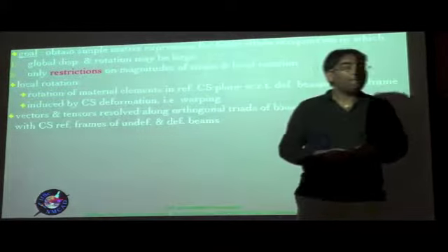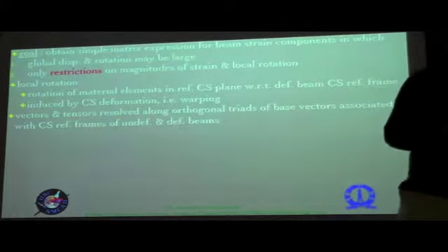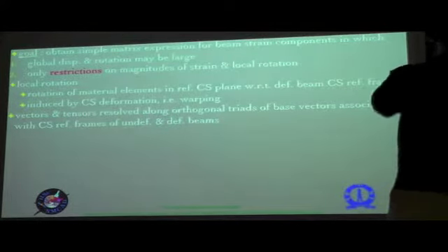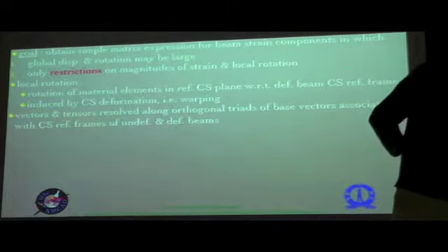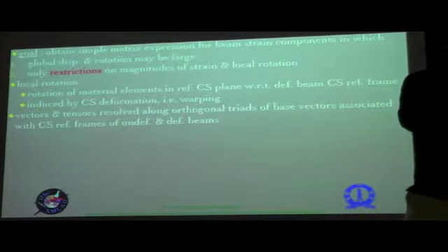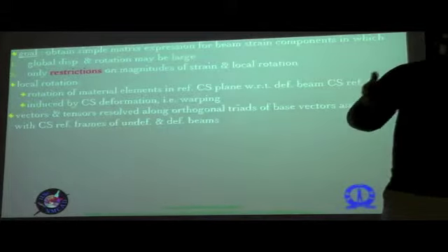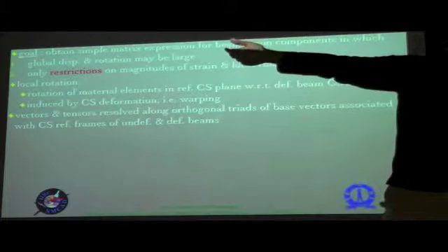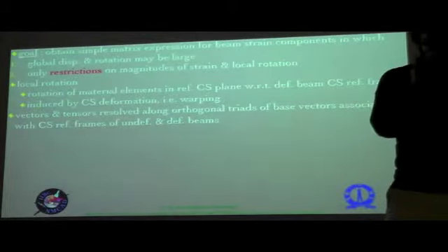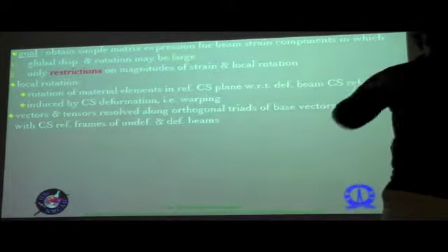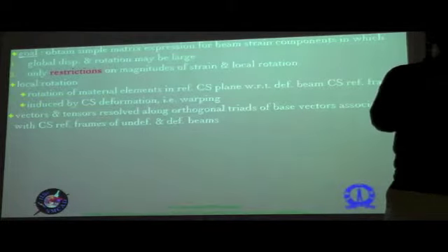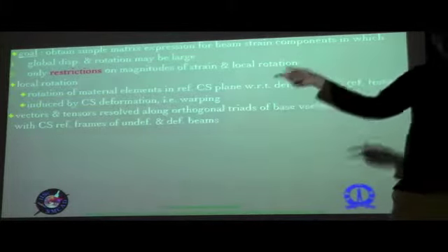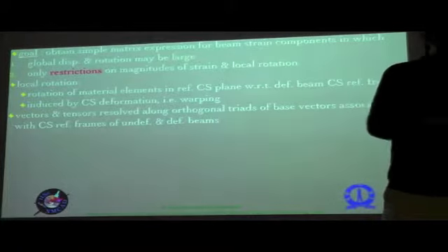So is this restriction also applicable in the case of hyperelastic material? For hyperelastic materials, the strain that you have to talk about has its own limits. The restriction on strain is basically for elastic materials. For hyperelastic materials, there are some materials which can go all the way up to 400% strain, etc. In that case, the maximum strain epsilon is not a small quantity compared to unity. So you have to completely drop that out and deal only with the geometric small parameters that you have in the variational asymptotic method. So many of these conclusions that we are making will not hold for hyperelastic materials.